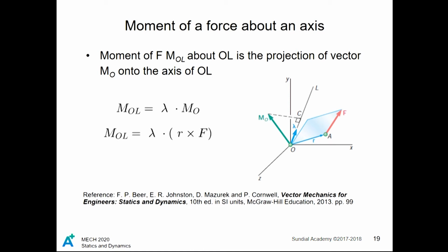To find moment about a specified axis, we first find the general moment axis using the given force and radius vectors, then perform dot product multiplication with this maximum moment vector and the desired moment axis. This method allows us, in its most simple form of the unit vectors i, j, and k, to separate the moment vector into its moment components about the coordinate axes.